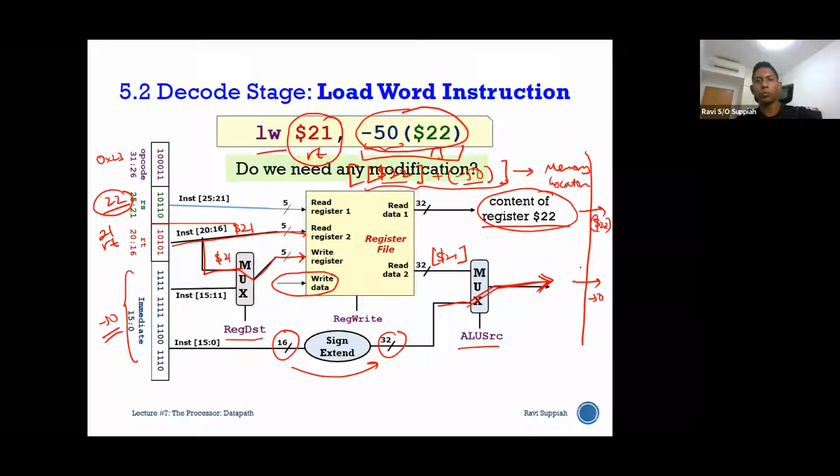All right, so of course we know the information because we looked at the decode stage. But if I mask out the decode stage and I look at what goes to the next stage, you only see two 32-bit data. Correct? Two 32-bit data is coming out of the decode stage and going to the ALU stage.